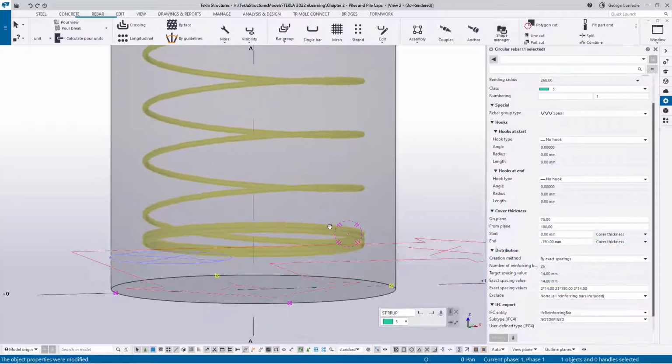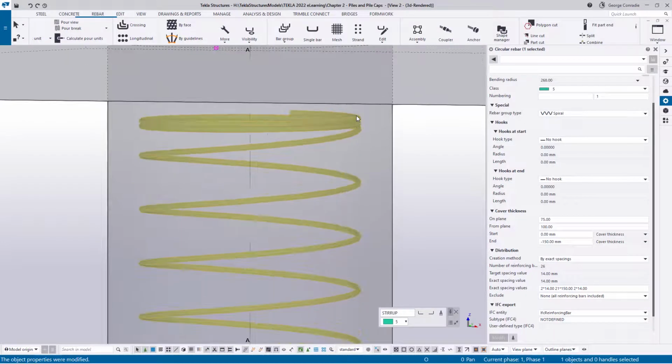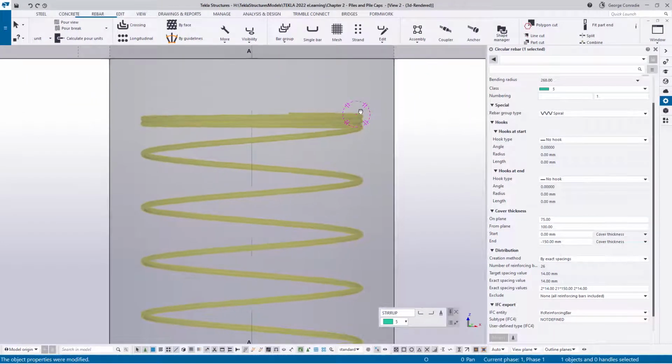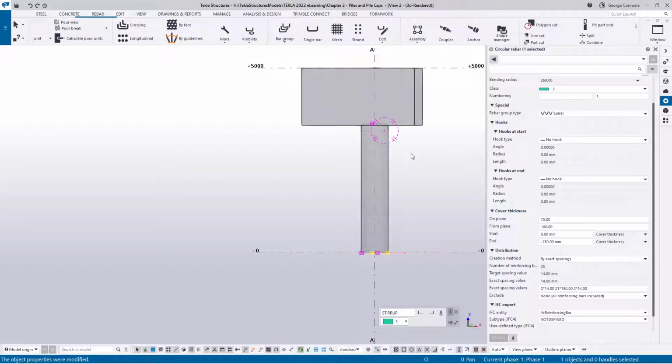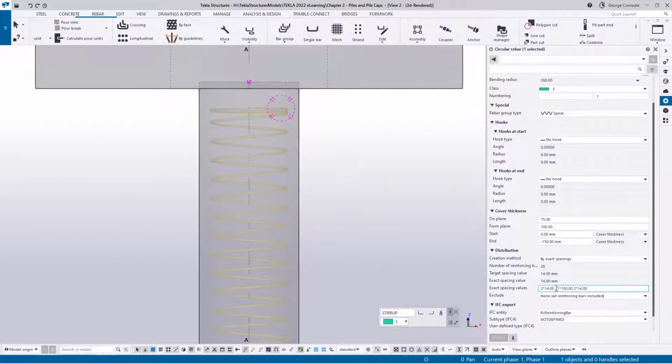So we get 3 rings at the bottom perfectly. Then we have our spiral at pitch at 150, and then at the top we've got our 2 again. Now you can see this one, if I go Control P, we've got a bit of space at the top, so maybe we can reinitiate the 22 again and just see where it gets. So it gets too high, so we're going to pretty much be limited with 21.